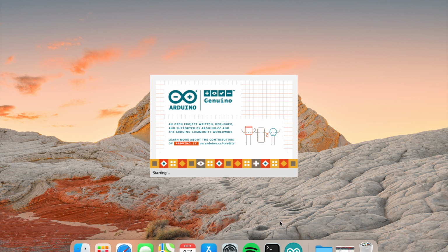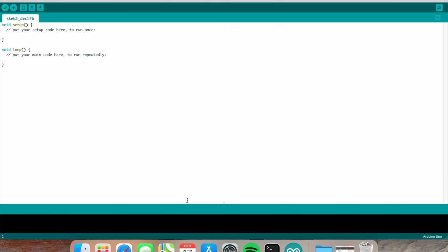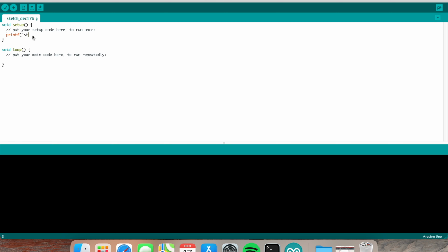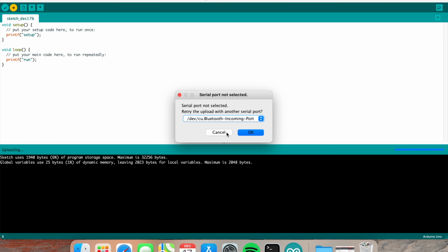Now, in order to program it and upload the C code, we need two things. We need the Arduino IDE, and we also need something called the AVR toolchain for the upload. The Arduino IDE is very straightforward to install and appears to work well under Rosetta 2. However, because I don't have my Arduino board on hand, I couldn't test if the IDE would communicate with the hardware. I suspect it would work though, seeing the IDE correctly identified my MacBook's various ports.